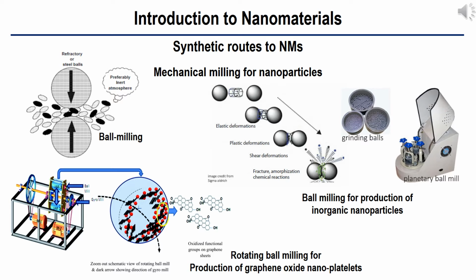First of all, let us think of top-down methods such as mechanical attrition, where the material is prepared not by cluster assembly but by the structural decomposition of coarser grained structures as the result of severe plastic deformation. This has become a popular method to make nanocrystalline materials because of its simplicity, the relatively inexpensive equipment needed, and the applicability to essentially the synthesis of all classes of materials. The major advantage often quoted is the possibility of easily scaling up to tonnage quantities of material for various applications.